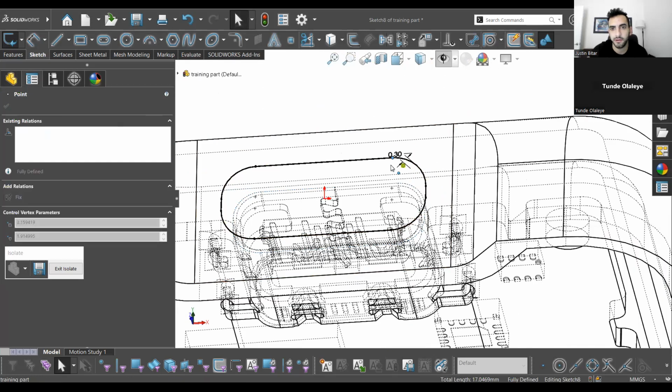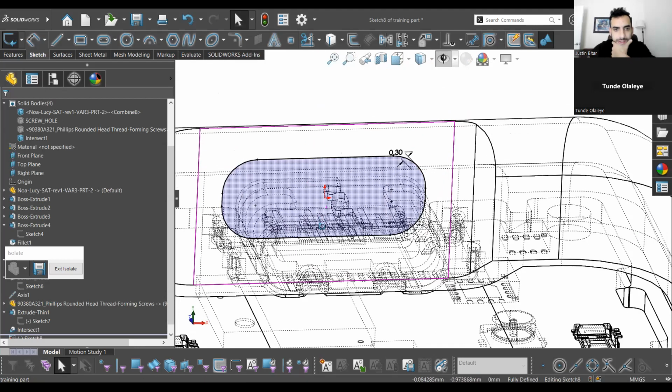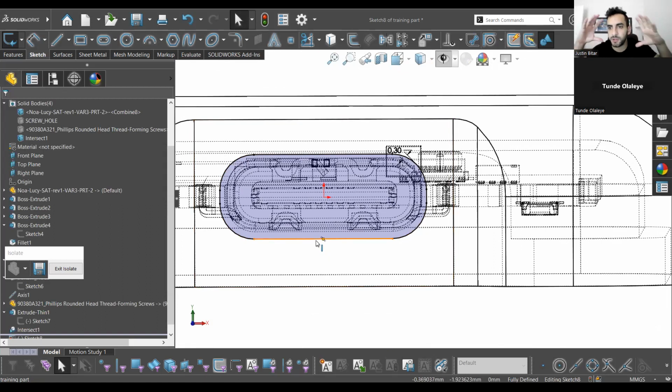Okay, so check this out. We'll just drag this guy over. Look, fully enclosed sketch now. And it's just 0.3 millimeters larger than the actual USB-C port. This will help us insert one of these cables into the hole there. You need to have a slight clearance there.